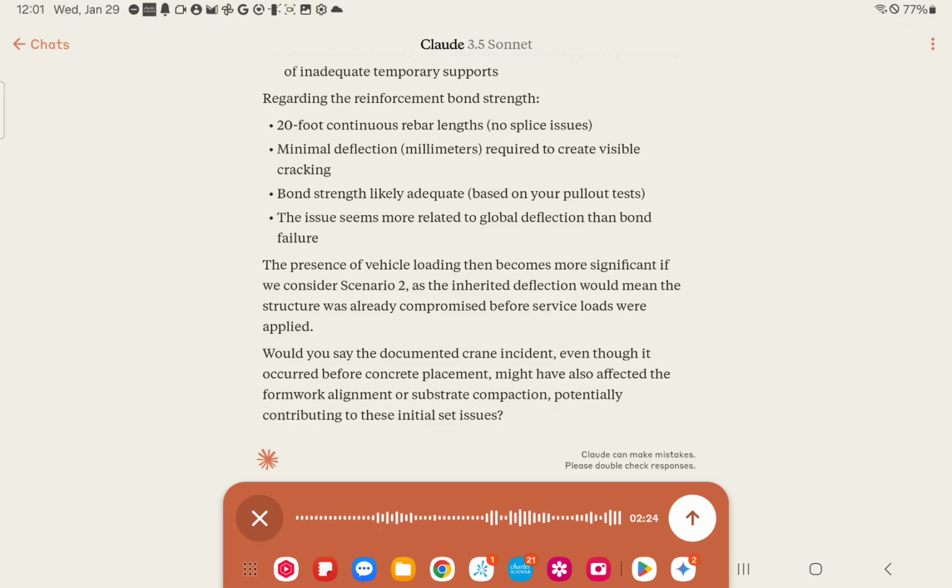So we have some columns in the car parking area that I described to you first, the pool deck sitting on top of column heads. But in the parking garage area, we have the same pool deck. Now it's the parking area, same elevation. It's now anchored face mount, if you will, to the columns that go up into the tower of the building. And when I say face mount, it means that initially the concrete went over the columns, and then they built columns on top of the deck. That's what I can't confirm.